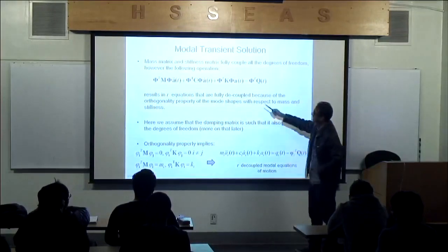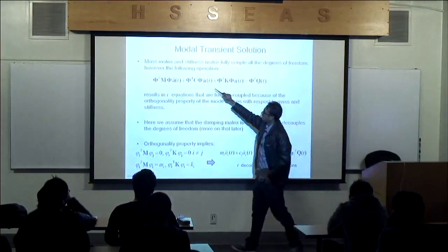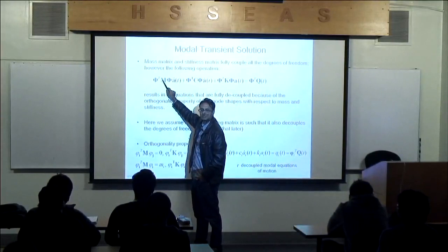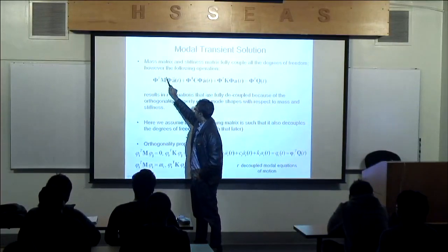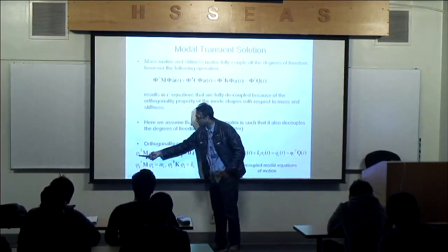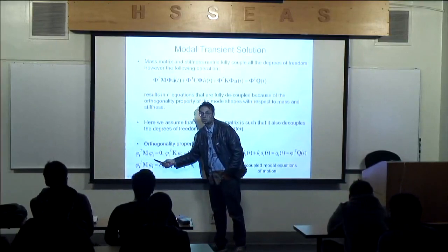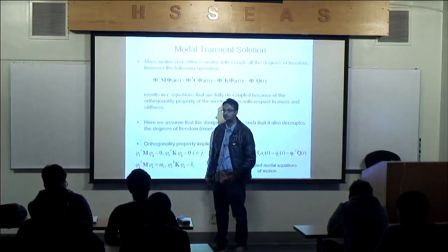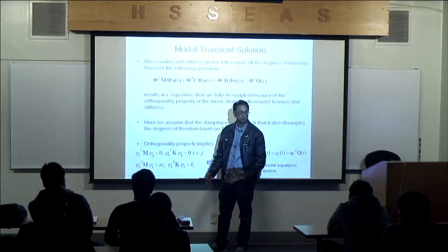And what's more is that these eigenvectors, or mode shapes, are orthogonal with respect to the mass matrix. This is basically going to give you a diagonal matrix. So if you take any two different modes and do this calculation against the mass, you'll get 0. It's insane. All the off-diagonal terms will be 0.